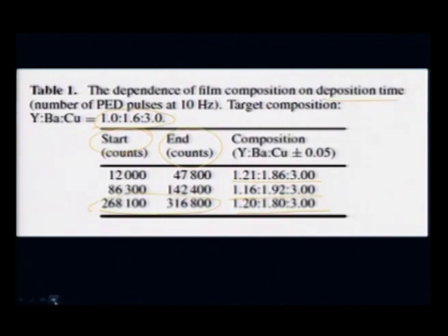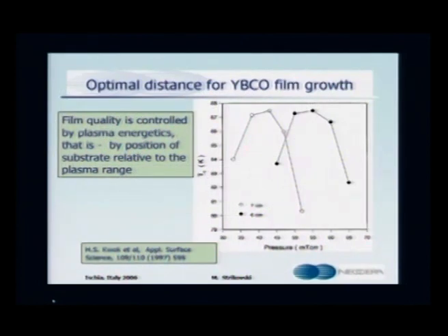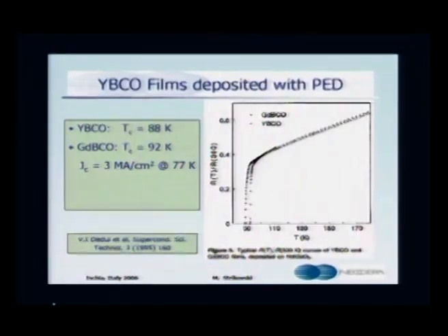So you need to have some idea how the chemical composition can vary, and also the distance between target and the substrate is determined. If you are going to keep it at 6 centimeter, you can see the Tc is varying as a function of millitorr of oxygen partial pressure. If you are going to keep it at 7, then you can see you can achieve a good stoichiometric film even below 50 millitorr. So all these are very sensitive and one depends on the other, therefore depending on the system we need to make a compromise, and these are some of the superconducting films.